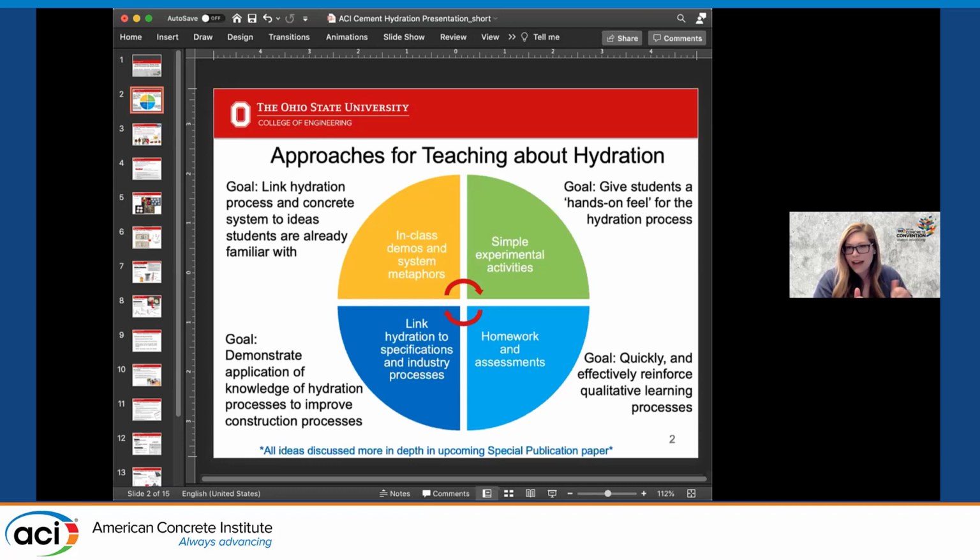But one key with that is that you want to make sure you have a baseline set of tests or requirements for those systems. I was having students submit mix designs for like one cylinder this semester, which obviously isn't going to make a good experiment. So if you can, make sure they're running slump, make sure they're running air, doing a couple compressive strength and a tensile strength cylinder, or using your resistivity or other setups. That can be really helpful.